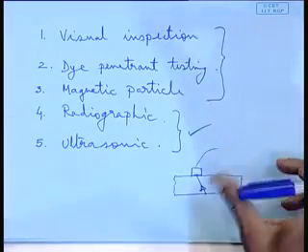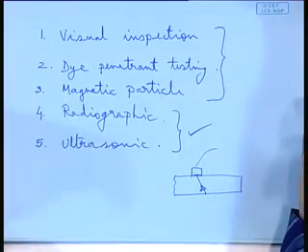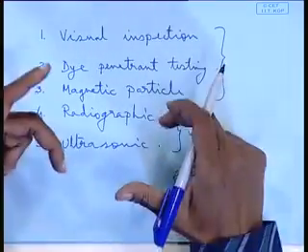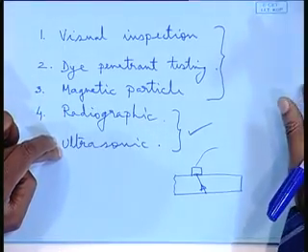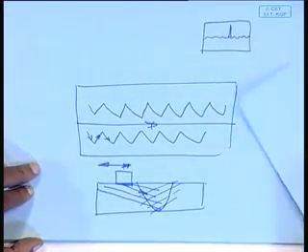There it becomes very important to say that, well, these weldings were tested and these are my reports. But with visual, dye-penetrant and magnetic particle, there is no report. The report is man-made, meaning after you have seen, you can write it down. But here, reports are generated in the process of testing, the photographic films or the prints from the ultrasound probes, right.